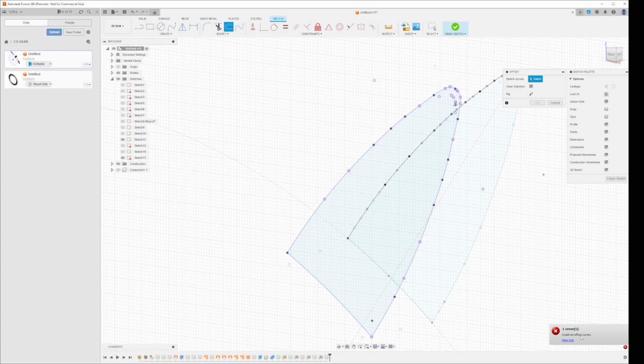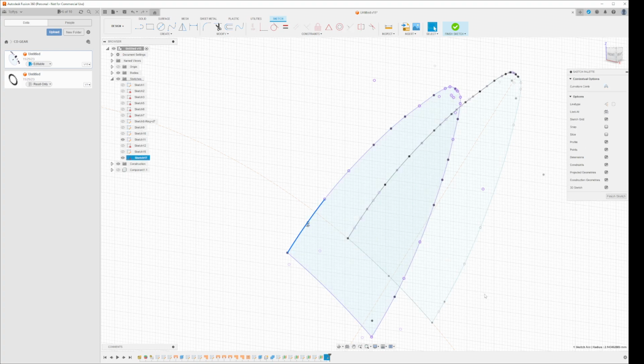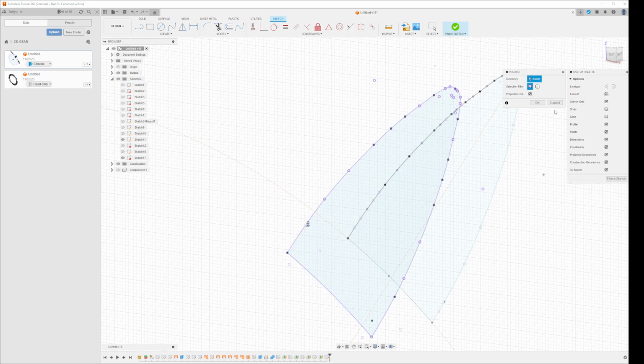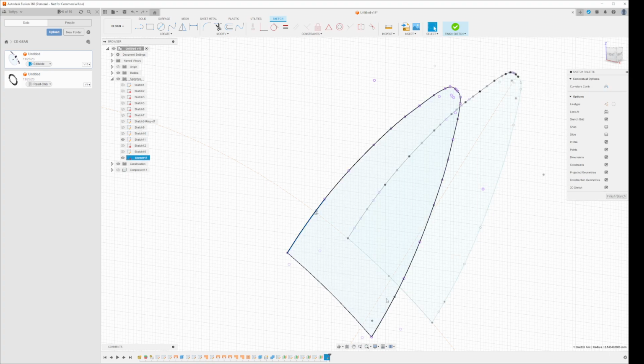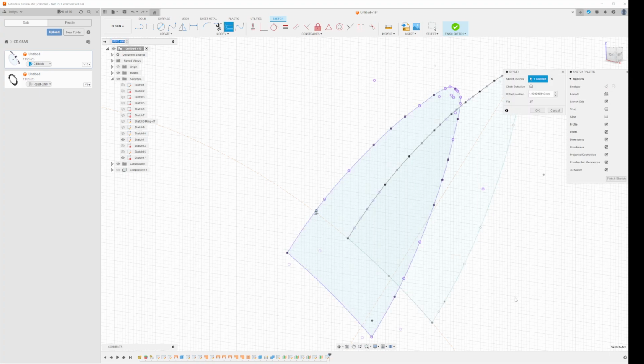Now the problem is here that you have overlapping lines in the structure, and I'm going to show you exactly where that is. If I go and click on this one, I want to offset, so I click offset, select one, and I click offset. You see one is selected. Now I don't need to hold Control. Just double click. Double click, it doesn't do anything now, but you have to select it. So here, here, here, here, here, and here, and here.